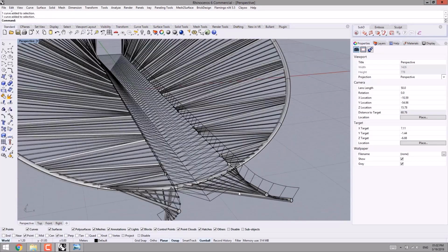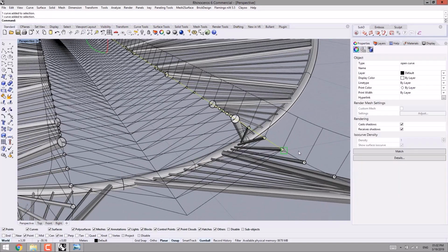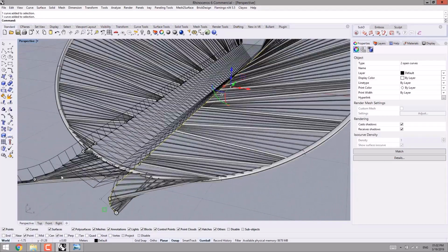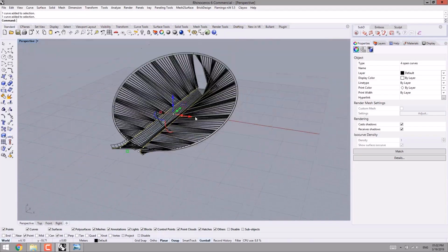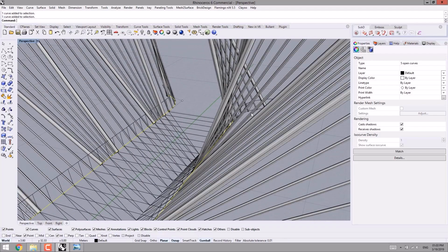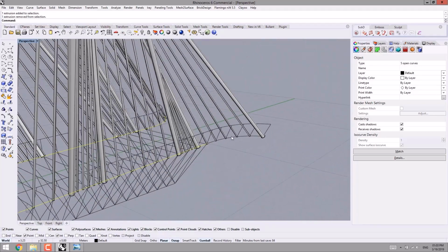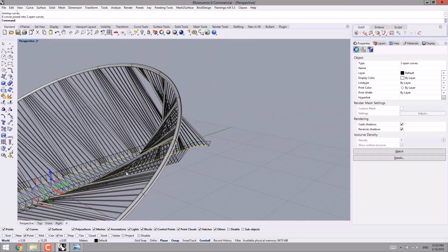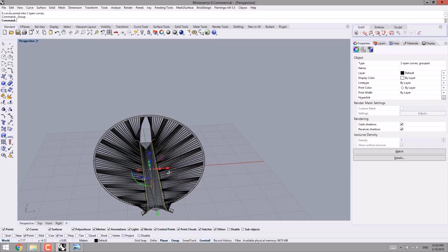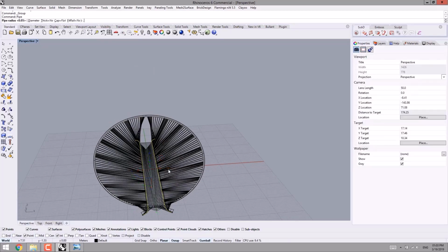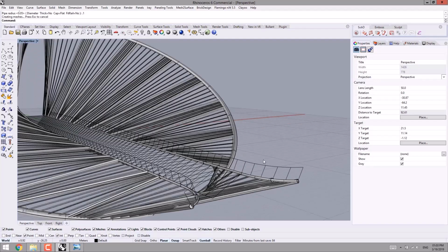After that, I'm gonna select the lines of the bridge, but before that I should join them since they have been exploded. So at first I select every single part and this one. Then I click on join command to join these lines. Then Ctrl G to ungroup them. After that, pipe. Then I should specify the pipe radius, 0.1. It is enough. Check it out.